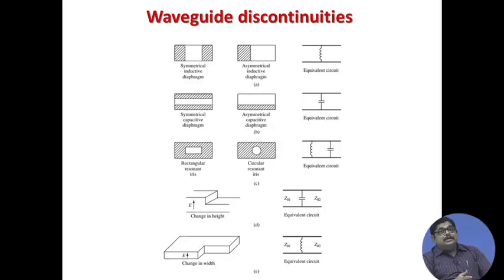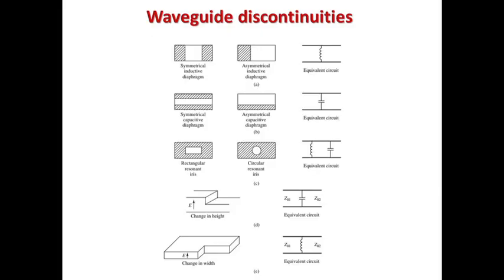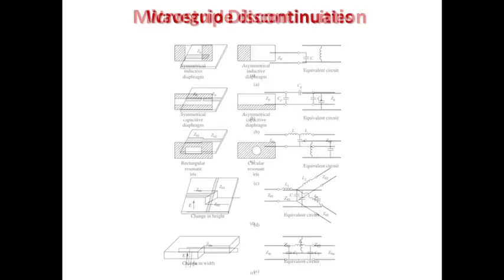At high frequency we cannot fabricate lumped LC, but this is the way we fabricate LC at high frequencies, and you can measure their S parameters by a network analyzer. So, to give you an idea, at microwave frequencies these are the equivalents of the lumped things; here we do not use lumped elements, but distributed elements.